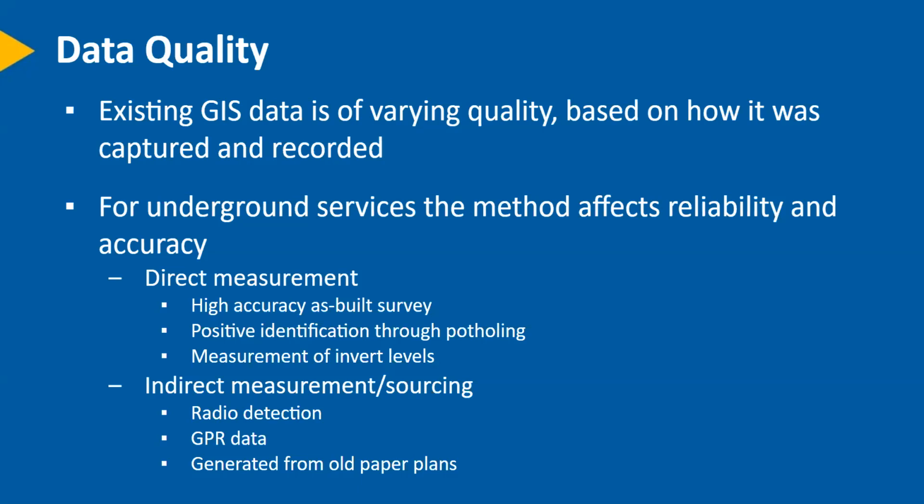And it all does have direct applicability to the use of that data, especially in something like augmented reality. So specifically for subsurface utility engineering, the direct measurement of features underground, whether they're using potholing or directly measuring the invert levels for depth of pipe, depth of cover for oil and gas applications, or they might use indirect measurement of sourcing, things like radio detection or GPR.